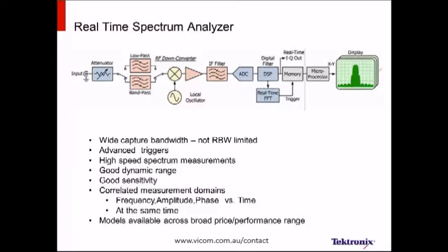But because we are looking at the spectrum from an IQ perspective, I get to do what's called multi-domain analysis. I can look at frequency, amplitude, and phase versus time in a very, very correlated manner, meaning if I put a marker in one domain, it automatically tracks in another one. Now from an EMI scanning perspective, that's not helpful, but from an EMI diagnostic perspective, it's very helpful.